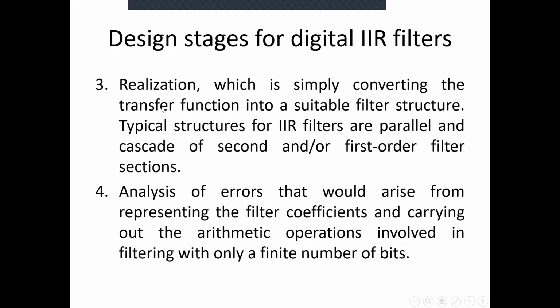Now, realization is simply converting the transfer function into a suitable filter structure. Really, we are going to talk about representing the filter by some delays, multiplication, addition, and subtraction operations. Point number 4, analysis of errors that would arise from representing the filter coefficients and carrying out the arithmetic operation involved in the filtering with only a finite number of bits. Of course, this point is very important.